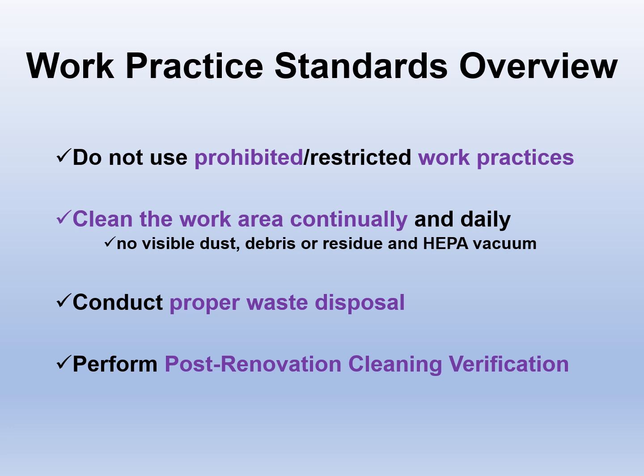In the work practice standards overview, do not use prohibited or restricted work practices, as we already covered. Make sure that the work area is cleaned continuously, daily. And what does this mean? This means no visible dust or debris or residue. You're using the HEPA vacuum along with wet methods in this process of cleaning. You are properly disposing of any waste that's collected. And you will perform a post-renovation cleaning verification.